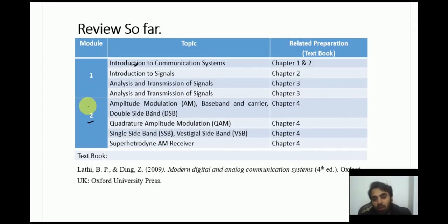So we advance towards double sideband large carrier, or amplitude modulation, in which we send the reference signal, or the pilot, alongside the message signal. And then on the receiver side, we usually just use a simple circuit that includes a resistor, a diode, and a capacitor to recover back our message signal on the receiver side, right? But both of them,